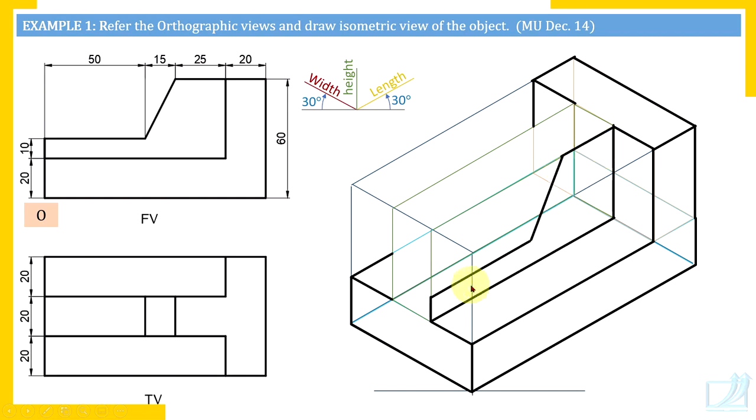Now the same shape is on the back side. So you are going to draw these edges here on the back side surface. Back side in the sense, check here. This is the plate, vertical plate. Its front largest surface has this particular shape and the same shape is on the back side. So construct that. Set roller with these lines and roll. 25 mm long edge, 10 mm long edge, 50 mm long edge.